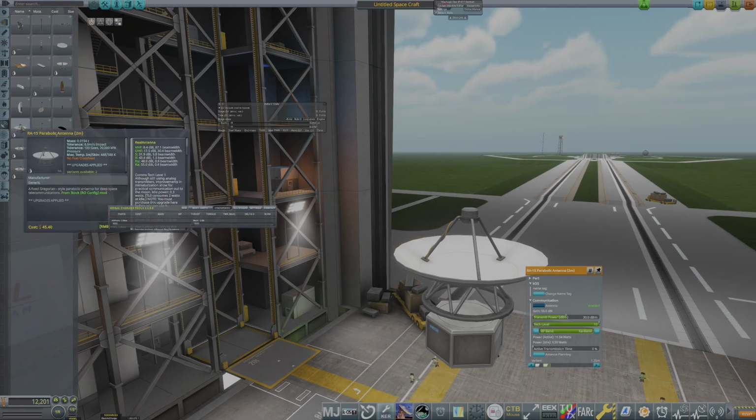Let's take the higher bands and look at the info of the antenna itself. I don't know if you can read this, but there is also a property called beam width. Say you take the Ka band, where you actually have the highest gain, but it only has like 0.4 degrees of beam width. That means the beam itself is more or less like a laser. So if it focuses on your ground stations, it will probably not even reach your craft. So the relay network won't work because it can only communicate to one craft at once.